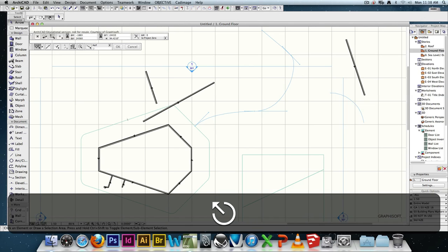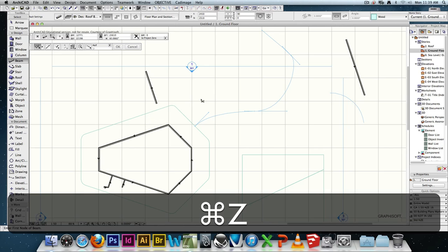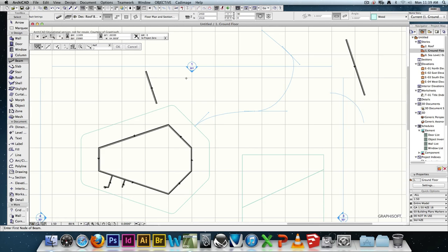And that works with anything. So if it was a beam, I know we haven't talked about beams, but if I want it to be 90 degrees to this, I can click on it, or I can draw any line, and that's 90 degrees to that imaginary line I just drew. Very handy. Cool. You'll never need to know an angle ever again. Of course, I could have added the angle from 1 to 1 and then divided it by 2 and then put A and then that number. But this is a lot simpler and quicker. Quicker? There's a new word. Quicker. Okay. Does that make sense?